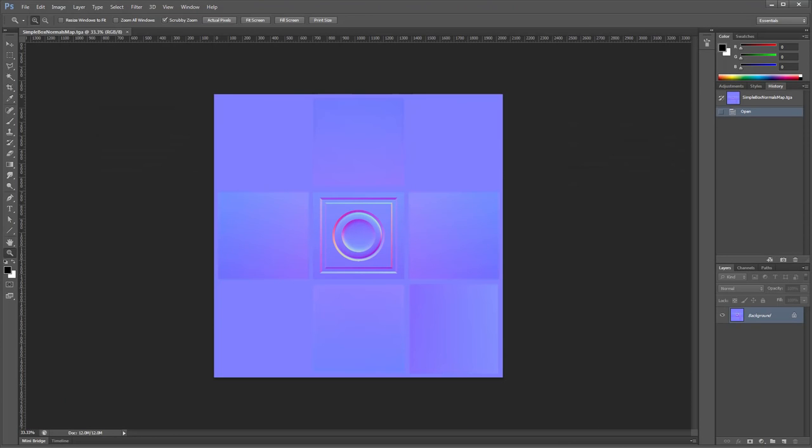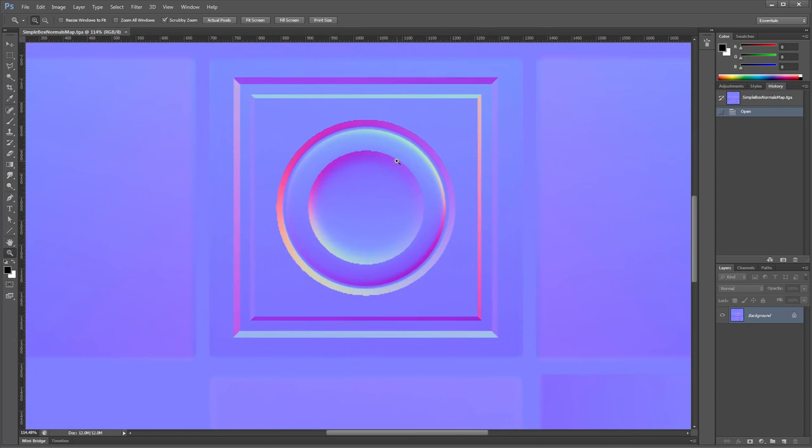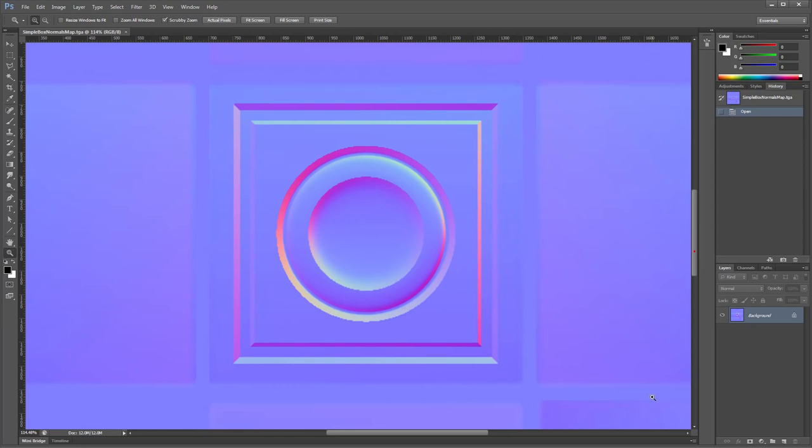To see it more clearly, take a look at this particular normal map in Photoshop. The normal map image is mostly blue, with very slight gradients on 5 of the faces of the box. What's more significant is the center square representing the front of the box. The two detail elements were used to create the multicolor information, basically telling 3ds Max to react differently at a pixel level. Each different color gives a very specific normal direction, and the lighting in 3ds Max reacts accordingly, even without the presence of geometry.